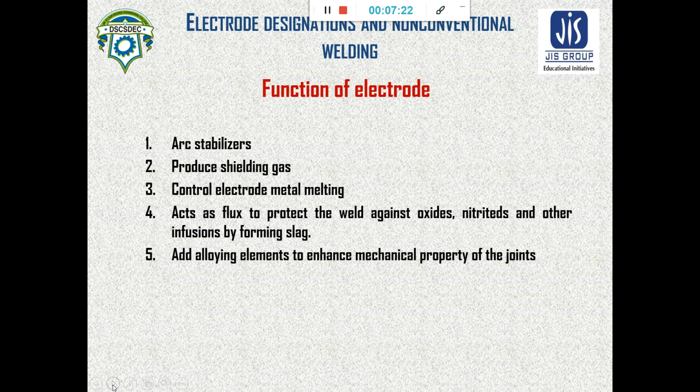Next, it acts as a flux to protect the weld against oxides, nitrides and any other impurities by forming slag. So slag formation takes place, and that slag covers the weld area, so that the weld area is not affected by the environment.